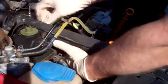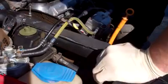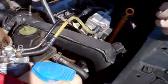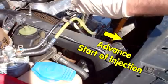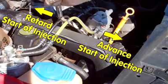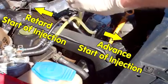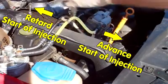Loosen the 13mm bolts on the injection pump sprocket, and then with a 22mm wrench you can turn the input shaft of the injection pump. Pulling the wrench towards the front of the car advances the timing. Pushing the wrench towards the back retards the timing. I will try to find a middle setting here and then secure the 13mm bolts.